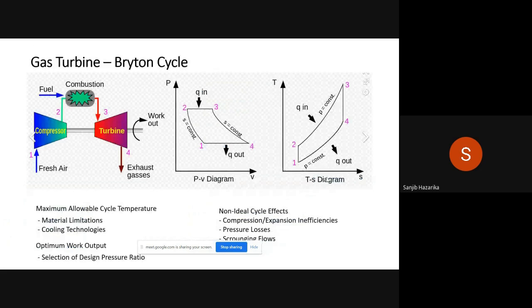And this is the principle by which gas turbines operate. It's a very ideal situation. We have a compressor. Basically, this compressor sucks in air, and then compresses it. Then we put fuel into the combustor, and when it burns, it expands, and then it goes to a turbine. The turbine expands it, and that energy goes to the shaft, and ultimately it goes to the electrical generator.